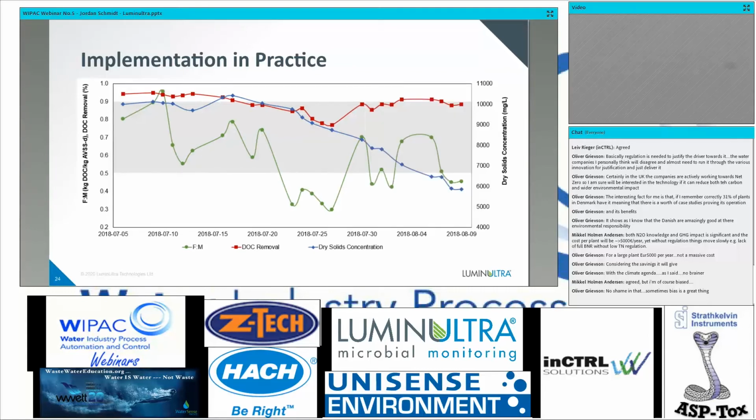Over the next few weeks, you can see the solids concentration had to be continually dropped down. This was due to a dramatic drop in the loading to the facility. But in general, they were able to. They had some issues with it bouncing in and out of the optimal zone, but they were able to keep pushing it back up and recover their treatment performance.